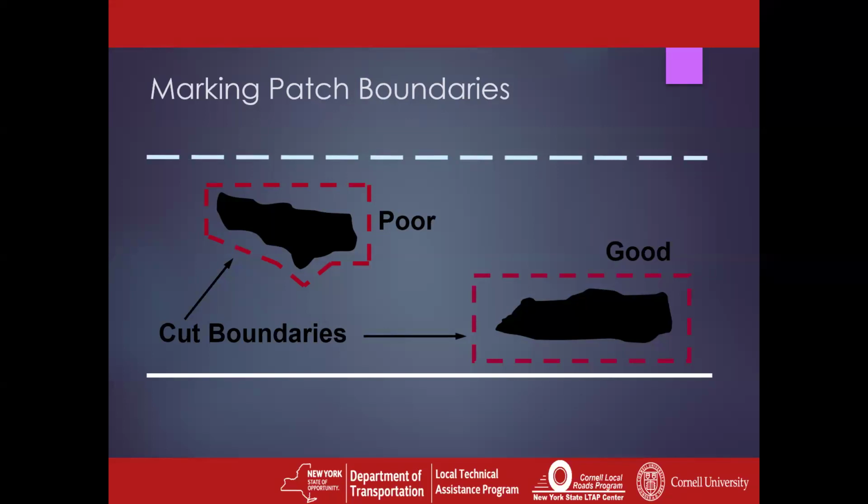Yes. Sealing is the technique you use if your cracks are moving. Does that answer the question, Jody? Yes, thank you.